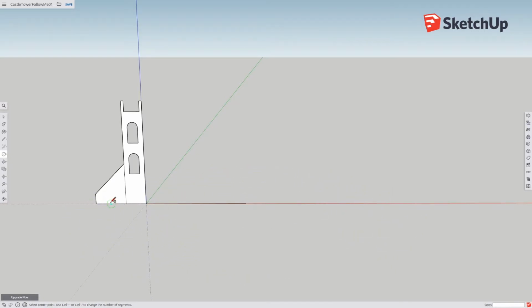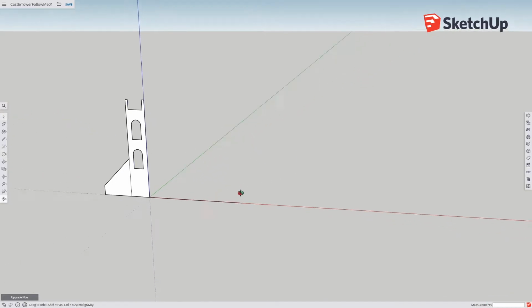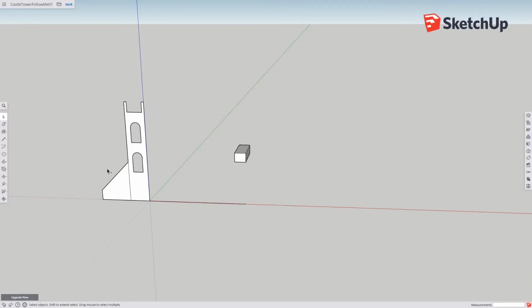Did you notice how the circle changed, by the way? When I bring it up there, it changes to that green axis. I'll just show you while we're at it. If I had the circle or the rotation tool, anything like that, where is it? There we go. It'll change colors depending on what plane it's working on, what axis it's aligned to. Okay, so obviously blue is straight up and down, vertical, which is really useful. And I should undo that.